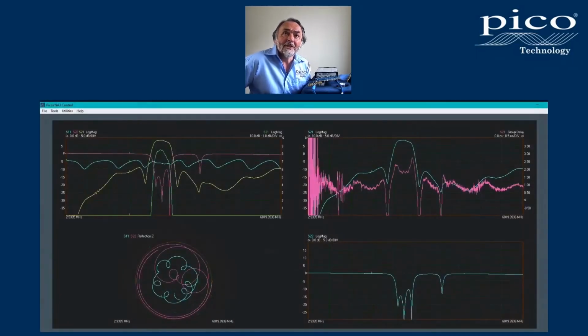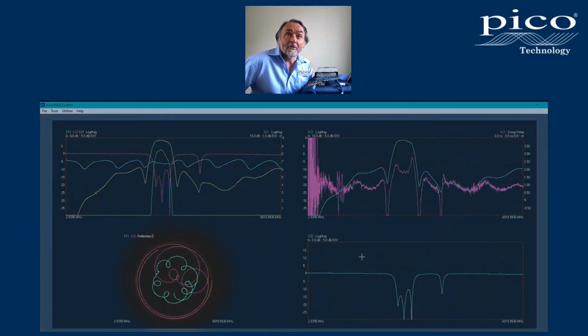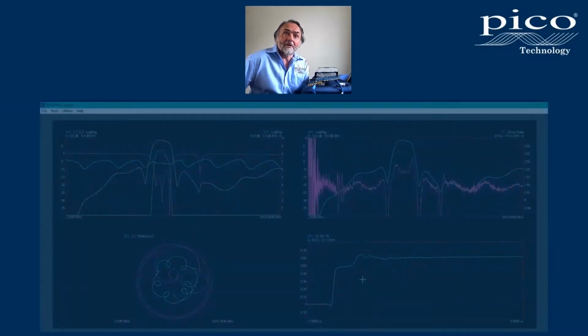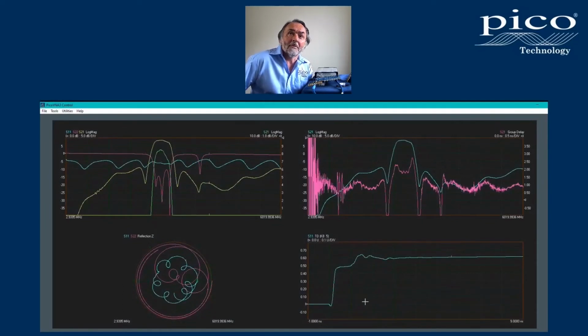Moving onwards, by adding 2 further display channels, we have a Smith chart displaying both reflection parameters of our network, input blue and output pink, leaving the 4th display channel available to display a time domain plot of a rather high input impedance match. A comprehensive and powerful display here of 9 live traces, up to 16 are available, very flexibly arranged by the user to suit the application and personal preference.